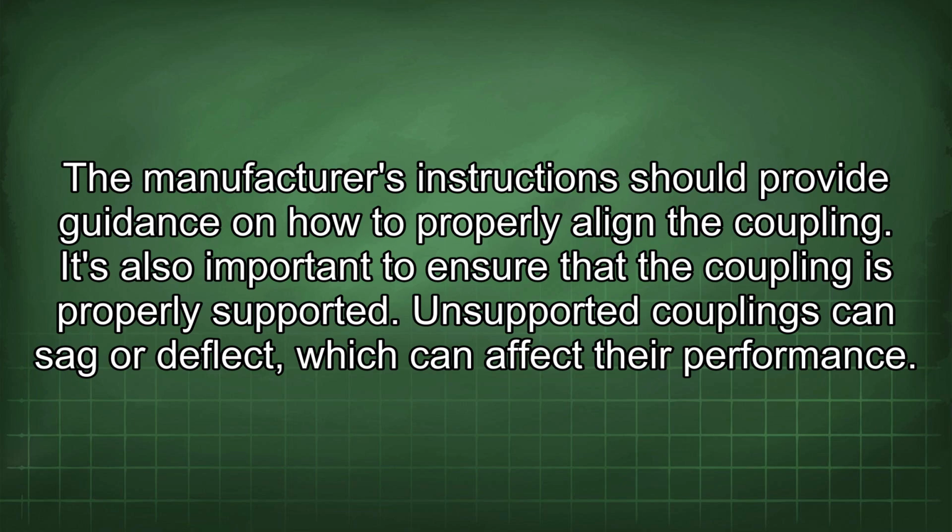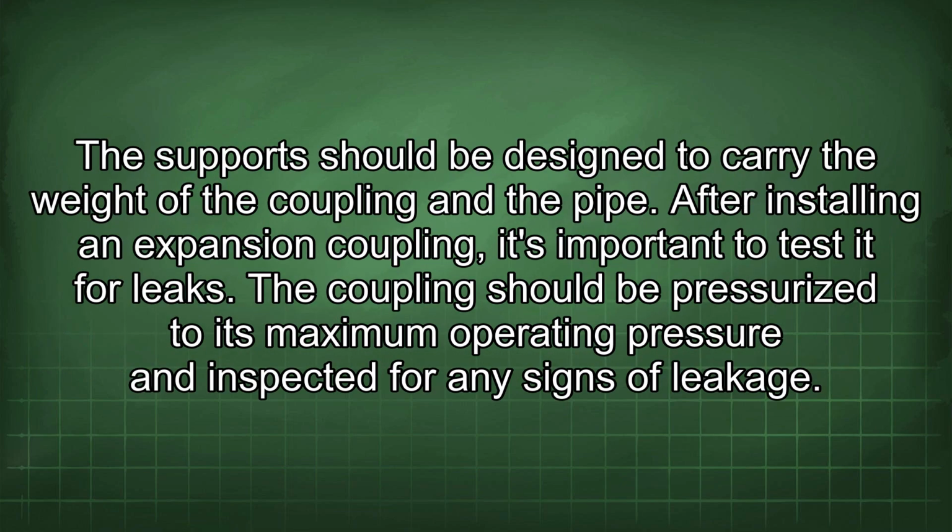It's also important to ensure that the coupling is properly supported. Unsupported couplings can sag or deflect, which can affect their performance. The support should be designed to carry the weight of the coupling and the pipe.